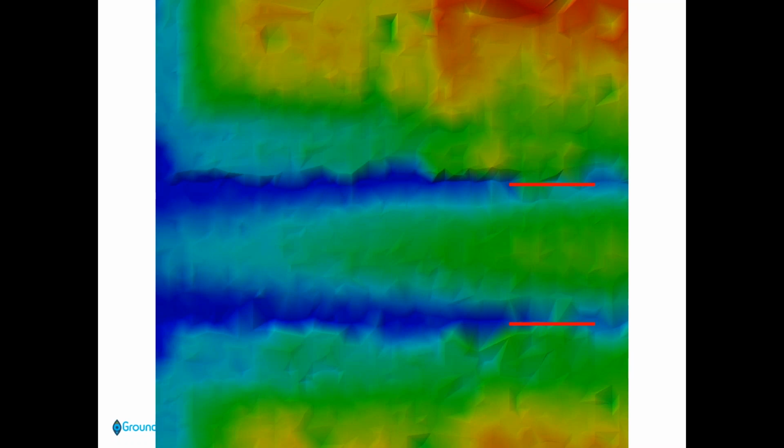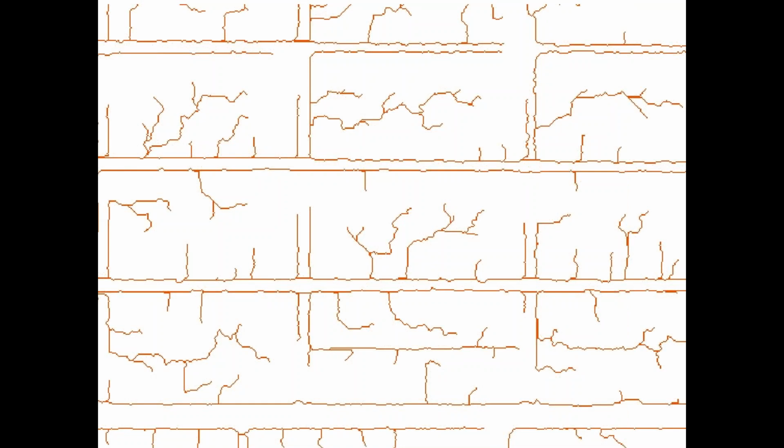So we go through the process of editing or modifying the topo surface so that it flows properly and reflects the real world correctly. And the result is a drainage surface or an artificial DEM. What you see here is an artificial stream network in an urban neighborhood built off a modified LiDAR DEM. And the flow goes clearly from right to left, and you can see clearly that there's flow on both sides of the street, in the gutter where you'd expect it.